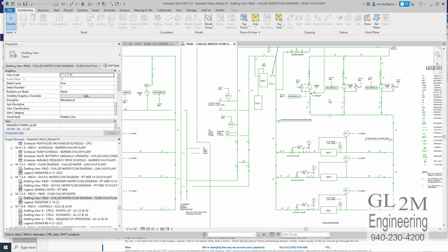As an example, these variable frequency drives all are specified with a bypass on them. So if the electronics were to fail, you can just run the electricity through the bypass, and that causes the pump to spin at 60 hertz instead of a reduced speed. That's not the end of the world. It means you're paying for that added cost of electricity that's not needed, and it means your differential temperature will drop, but the system is running. And that's what you want, the system to keep running.